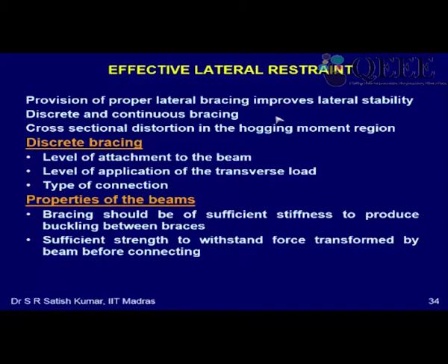So now for this reduced effective length, I'll again calculate MCR, and if it is still lower than MY, either I can use that MCR as the design strength, or if I want to increase it, I'll have to give additional lateral support, right? So that is how we have to go on giving extra lateral support until the MCR goes above MP, and then we can say that the beam is now laterally supported. Okay, so that is one part.